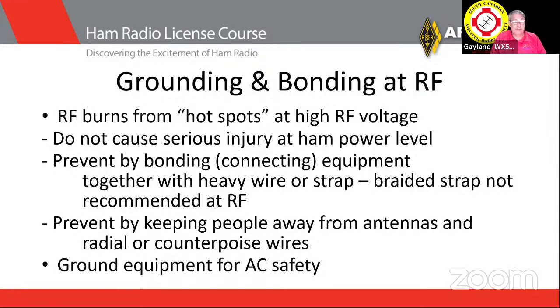Here's the big deal, particularly if you're operating some sort of portable or mobile setup. You want to keep people away from your antennas and the wires on those when you're transmitting. This comes into play during Field Day, big time, because we're setting up portable antennas. They're typically close to the ground. We're not on top of a tower somewhere where the antenna's a long ways away from somebody. We need to make sure that we keep people away from our antennas and that they haven't reached over and, oh, what's this wire, right as somebody keys up? Again, you want to not only RF ground them, you want to electrically ground them. Two different things here.